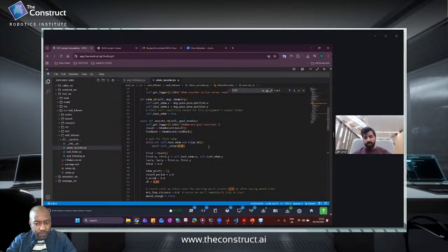So what could you have changed to have it work on the real robot? What could I have changed to keep it working? I think one of the ways was to increase the threshold, so it increases its window for detecting the start point, maybe from 5 centimeters to 20 or 30 centimeters. We could also use a timeout function so that after a complete cycle is completed, it can stop. And one advanced technique might be that we can set up some sort of landmark where it started and stop when that landmark is detected.